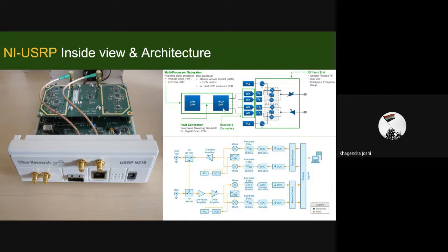There we cannot keep the laptop over the USRP, because the moment you disconnect this Ethernet port from the USRP, since continuous communication is always needed, the error will get thrown and your code will stop then and there, right? So for those types of scenarios, we need a standalone type of device, and those are also available with ATIS and NI. So according to the application, the USRP is used, right?